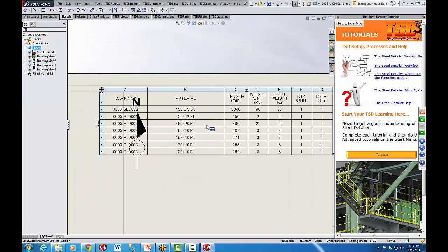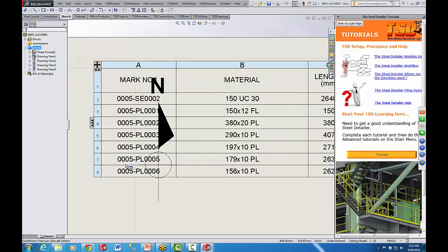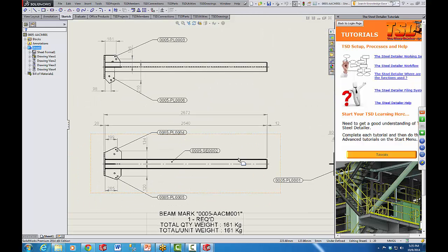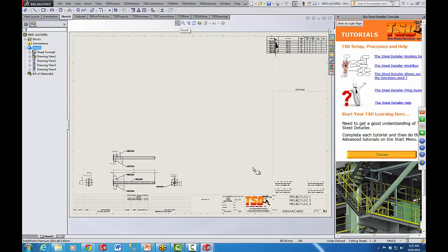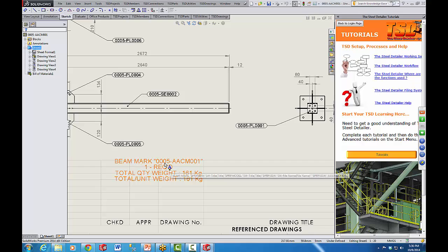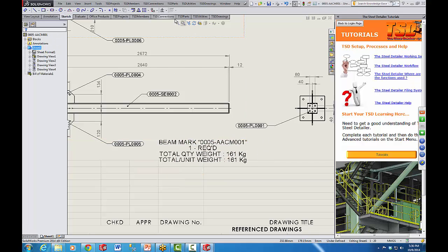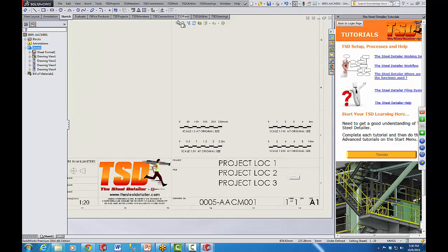You can see how all the BOM information has come through, and you'll notice now that all the sections and plates are nice and small in their file naming conventions. Locking does numerous things, and you can see in the plates that all the files and notations match what's in the BOM. It's also updated the quantity and the mass in the note. This note is used on our weldment drawings only, and the information for the project has come through on the drawing sheet.